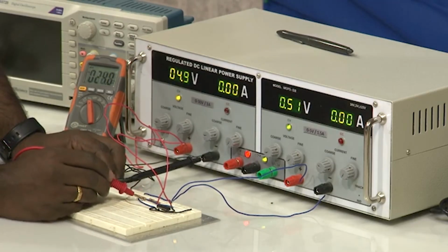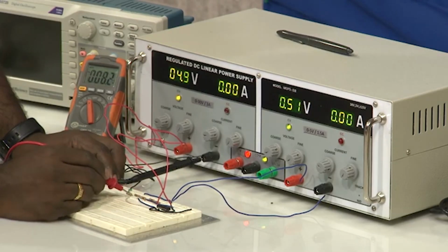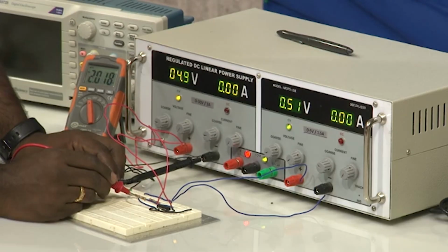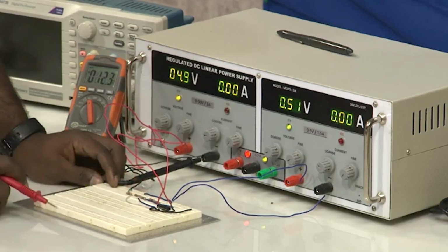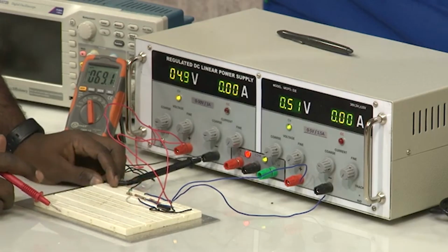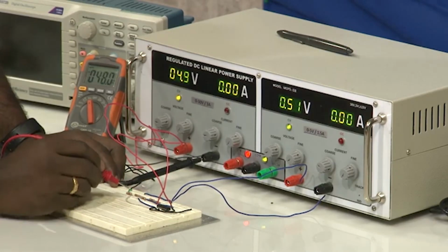So, if I see the voltage here, I will start with VC, the VC value is 1 volt, we can see, and the another voltage divider value is 2 volts, another value which is blue color one is 3 volts. That means, we know what is VA, VB, VC, which is passing through your comparator. Now, when we calculate C1, C2, C3, we can see here.